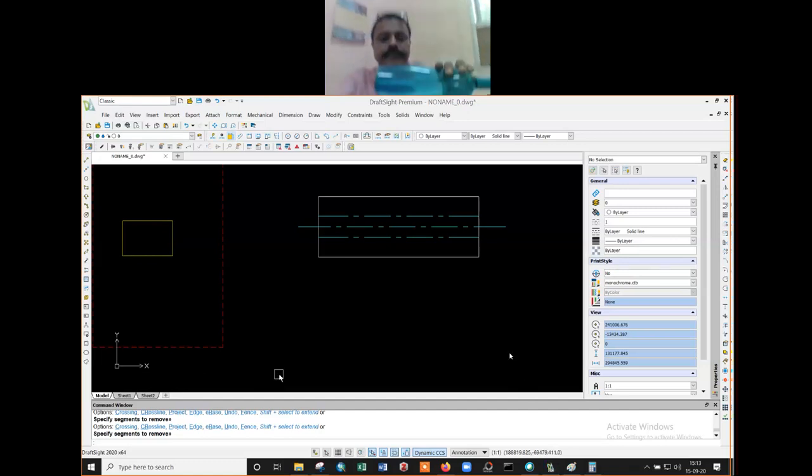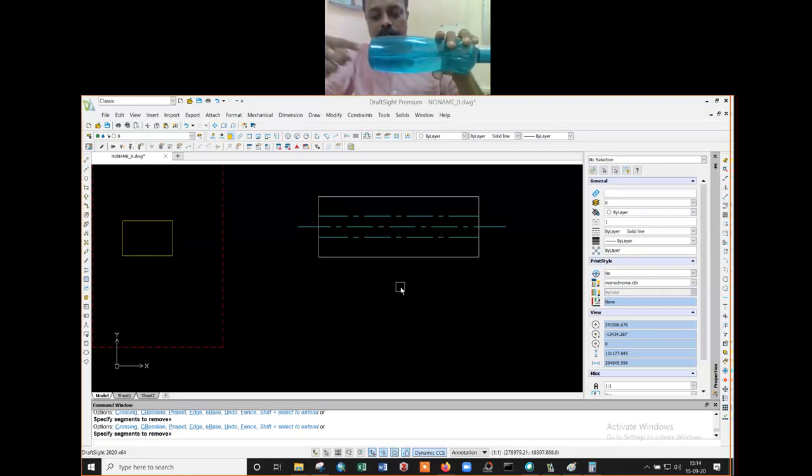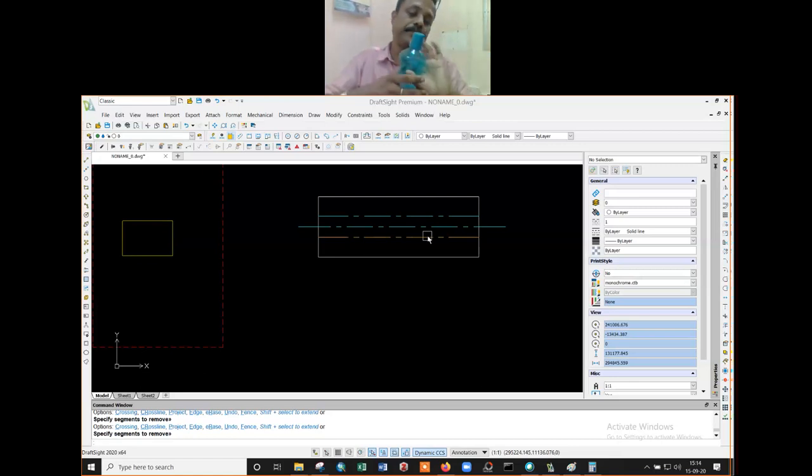Yes, anyone? Can you see this bottle? This is the same thing as you can see it on the screen. From here up to here, and then here up to here, you can represent it as a rectangular object. But if you drill through this solid object and make a hole, you cannot see this hole from this side unless you cut this part. But you want to show it in the drawing. So what line will these two be? Who can say? A hidden line.